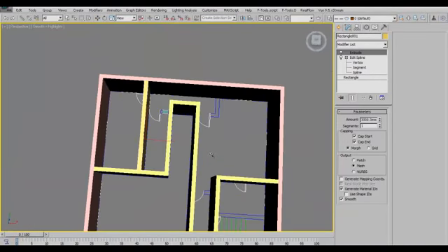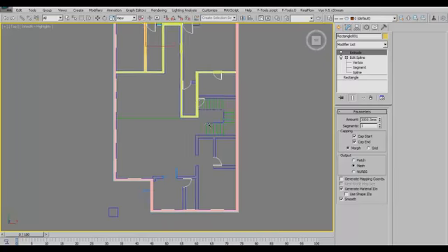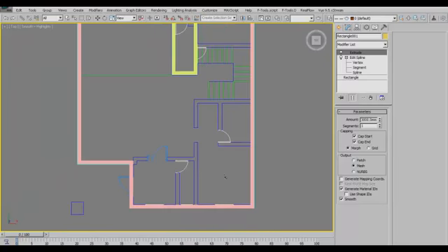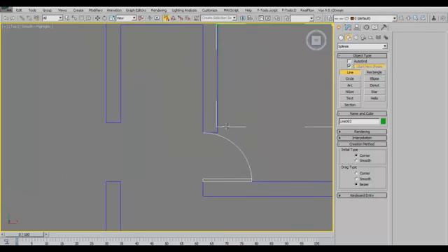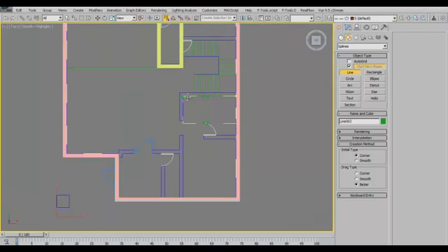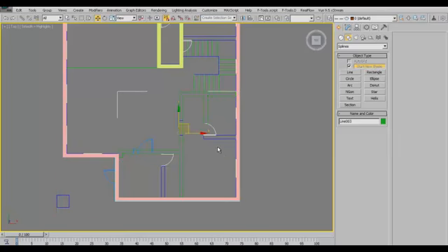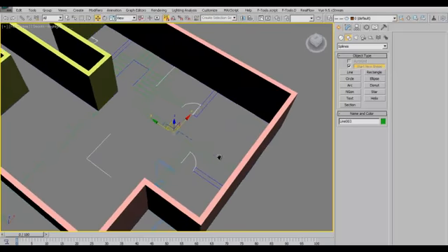So we'll go ahead and use another style, which is basically the line method, where we create everything by ourselves. Let's turn on our snap, come here, and zoom in to make sure we are picking the right point. Let's go down, because this is just going to be an opening. Then we pick this point, this point, this point. Take good note of all this, and you see there are 1,001 ways, whichever works for you. And it says close spline. You can see we've actually drawn our own spline.